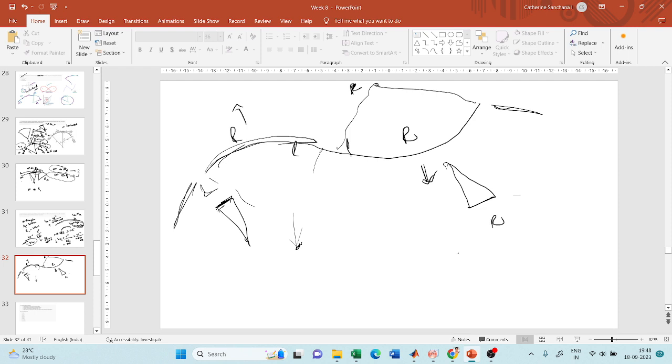So what will you do? You have to first bring this to zero. So from this you have to bring it to zero and then raise it in the opposite direction, right? You have to bring it to a camber and then raise it in the opposite direction. So what will you do here? You're going from R to infinity and then from infinity to R again. So this is nothing but the entire length of transition curve you have to find for these two cases, and you have to add it up, right?